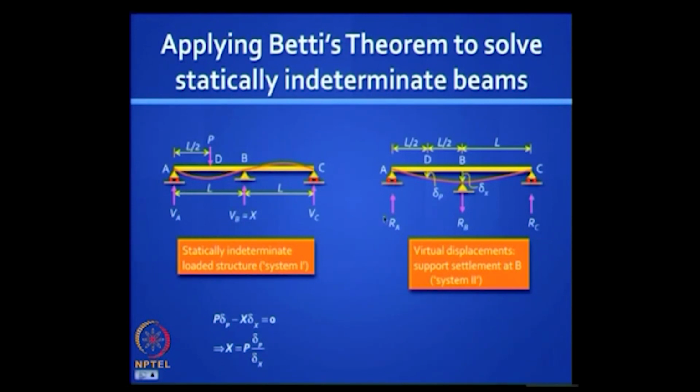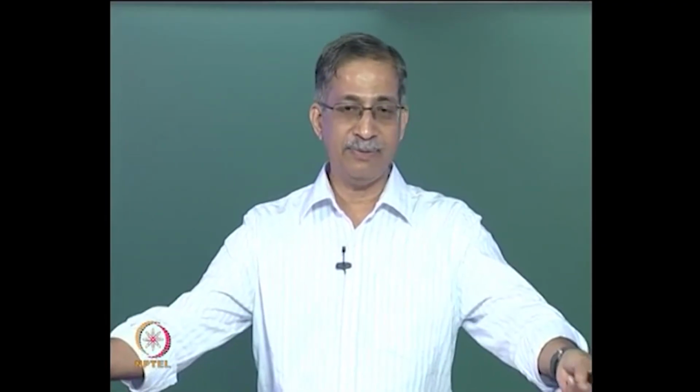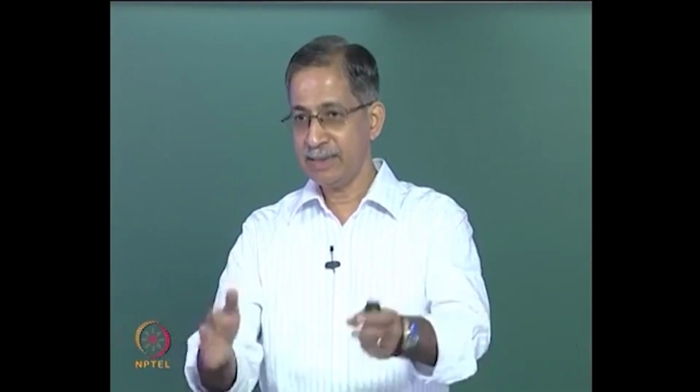which means if you take the ratio of this deflection to this deflection, that ratio times P is the amount of force that you get in this reaction. That is a fraction of P that is passed down as a reaction in the middle support. And actually in the early days they did measurements to prove it. Actually you can do this physically on a beam and measure the deflection, and that is your reaction. So it is a simple initial way of understanding indeterminate structures.